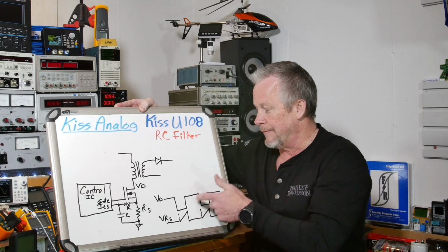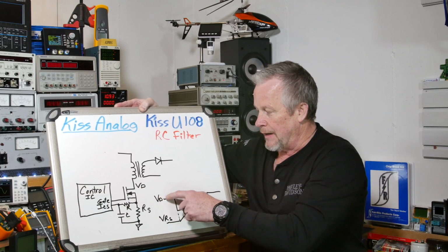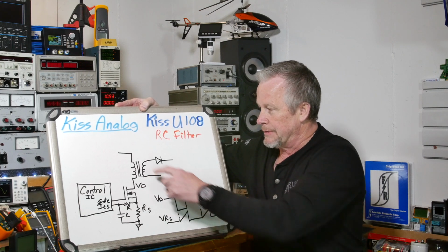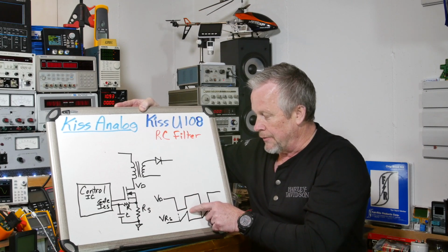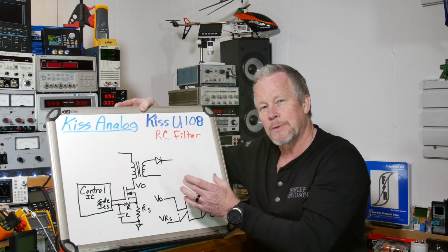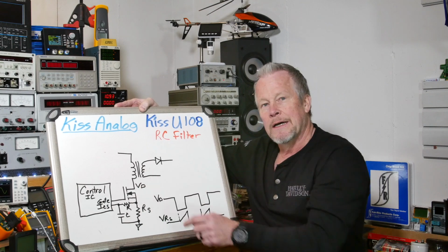So then the voltage on the drain bounces back up, it's off. So it starts off here, the FET turns on, pulls down, and pulls current through. When this rises to a certain value, he turns it off, boom. That's how a pulse width controls the duty cycle of this FET.